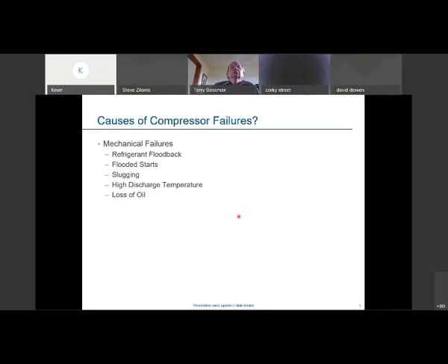So it's laying out in that system waiting for the proper opportunity to come flying back, and not paying attention to anything except the level of the oil in the sight glass. That could be a frozen up expansion valve or evaporator, something like that that's making the oil stay out in the system.